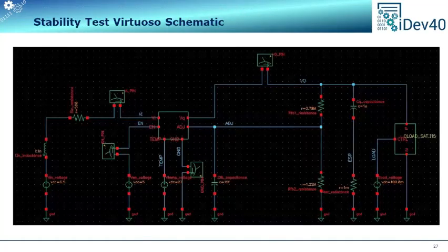Here you can observe the master test bench schematic, which represents a typical topology for testing a low dropout voltage regulator in simulation. Based on it, a netlist generator is used, along with additional automation, to generate a text-based netlist that will represent the final version of the circuit to be simulated. It contains a DUT, device under test, the actual LDO, the stimuli applied to it, the external capacitor, its equivalent series resistance, and the load current.